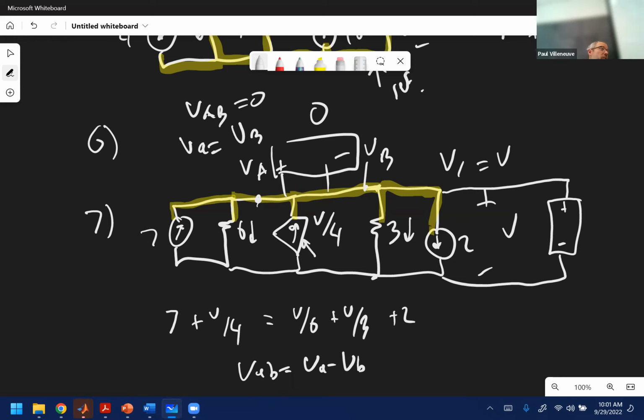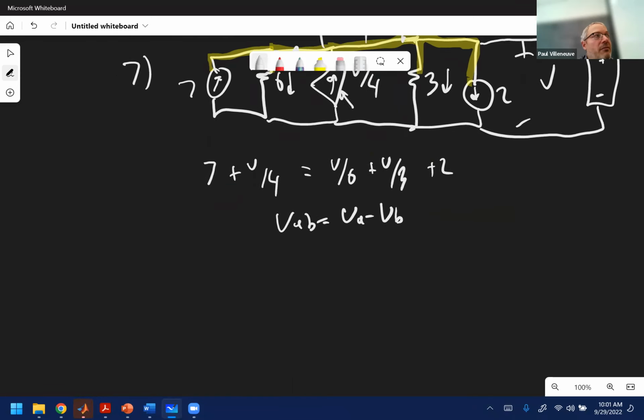As long as you're reasonably comfortable with a multimeter, most of us are really comfortable with voltages, currents. Some people forget you have to open the circuit and put that in series with it. Although you almost don't even need to do that now. Everybody know how you measure current now? Yeah, with the clamp. That's how you used to do it. What's that? You do a clamp-on. Yep.